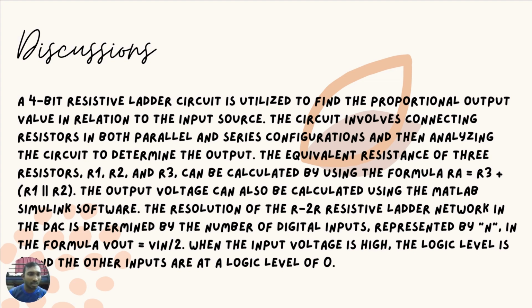We can see it in the figure just before this. The output voltage can also be calculated using the MATLAB simulation software. The resolution of the resistive ladder network is determined by the number of digital inputs represented by N. In the formula, Vout is Vin over 2^N. When the input voltage is high, the logic level is 1 and the other inputs are at logic level 0.